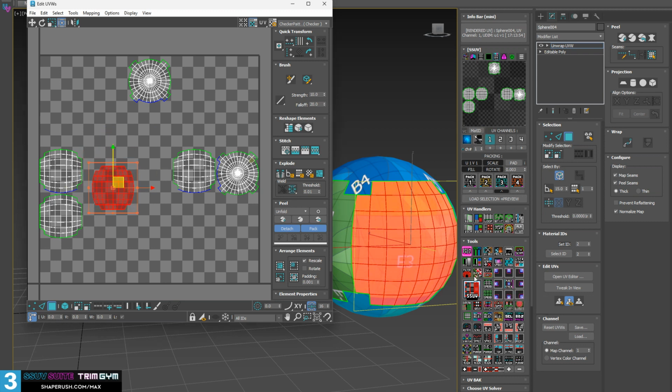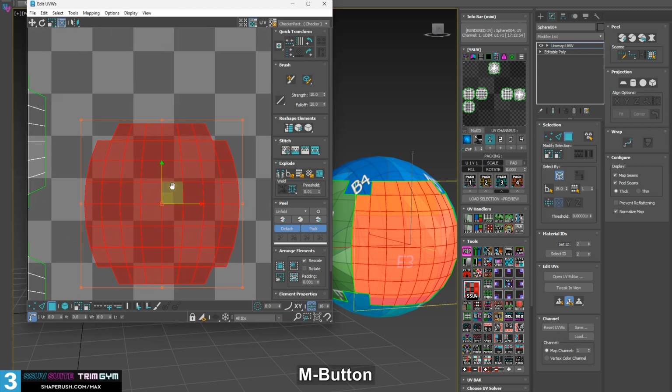That's perfectly fine. So what this does is this allows me to set a region by clicking. So I can left click and it sets the UV space for what I'll be doing next. That UV space is the minimum and maximum of this selection. So it's not where this top corner is and this top corner is, but it's pretty close to where that is.